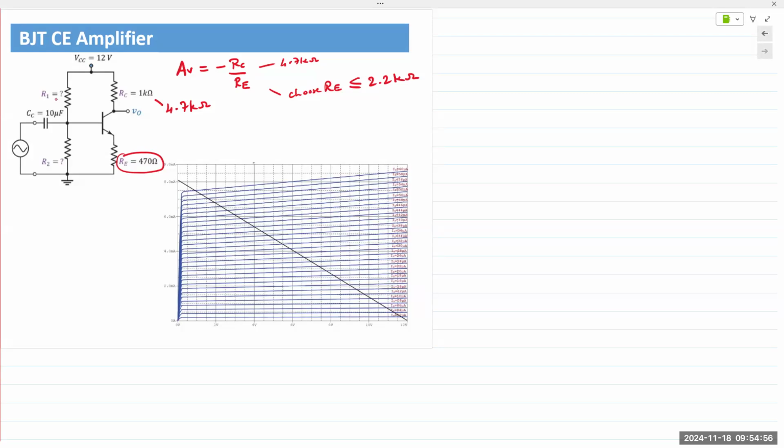These are the resistors in your lab kits. Cannot be more than that. Also, in the lab, we went up to 10 volts for VCE. You can extrapolate that to go up to 14, 16, or even 20 volts, which will be fine. Okay. We are going to do load line analysis when we are designing. We are given the value of RC. We are given the output. We need to find the values for R1, R2, and RE. Okay, in my example, we have chosen 1 kilo ohm and 470, so we'll roll with that. Now, on the output side, we already have the output KVL, but we need to draw the load line.